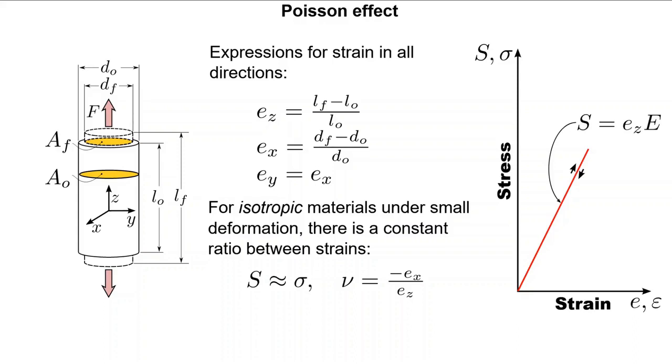As it turns out, there's another very useful material property which describes the ratio in which a component will deform in one direction versus others, if one were to assume that the material behaved the same in all different directions, as most metallic materials do. This latter description, behaved the same in all different directions, is an indication of isotropy. For small strains and asserting isotropy, there is a relationship between the transverse and longitudinal strain called Poisson's ratio,